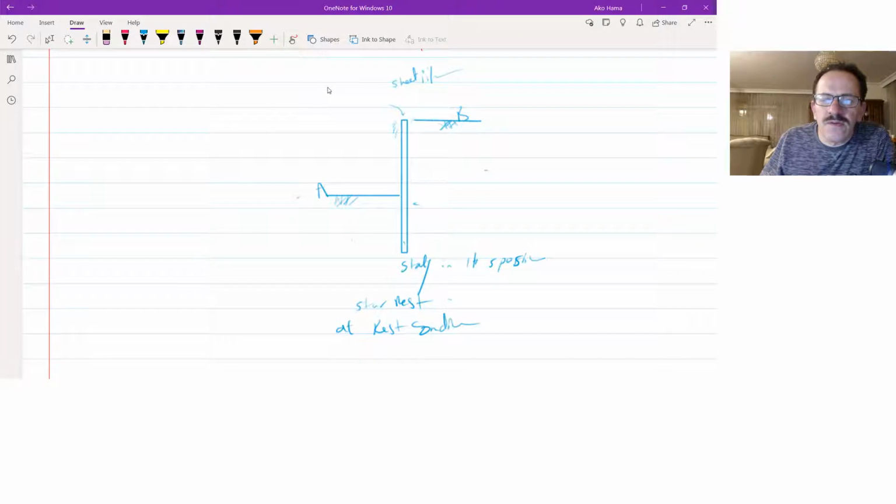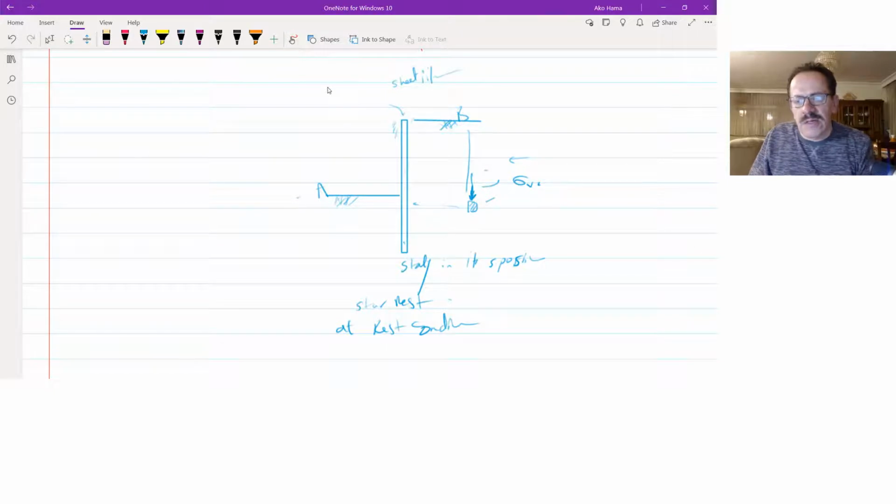What I want to see is the pressure that this soil, on my right hand, will exert on this sheet pile. Usually we have the vertical pressure on this element, known as sigma vertical, which is the volume of the column of soil on that element times the gamma of the soil.